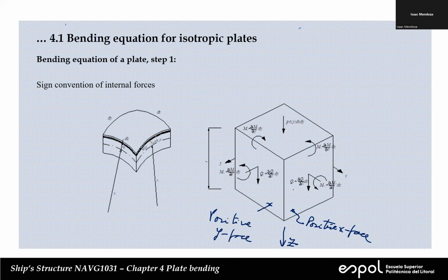So in the positive x face, this is the shear force, Qx. Positive shear force Qx in the positive x face points in the positive z direction. Similarly for the y case. So this is Mx, the bending moment.